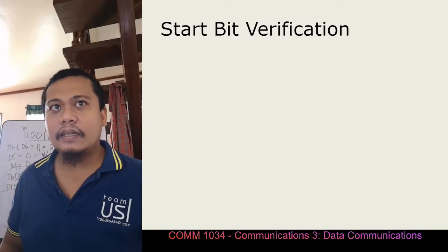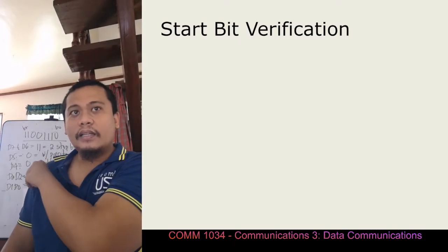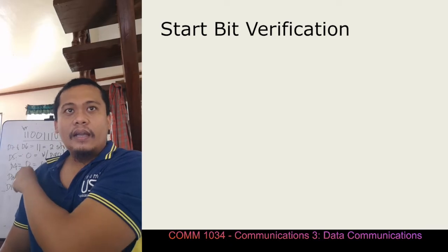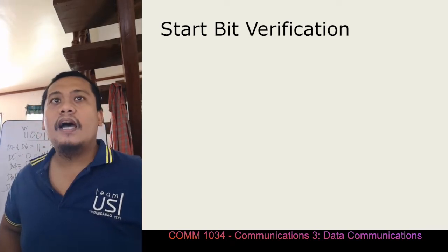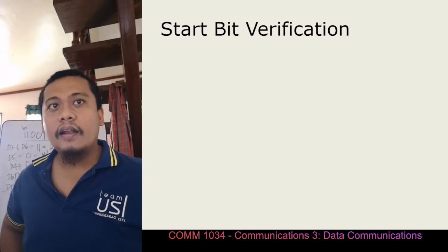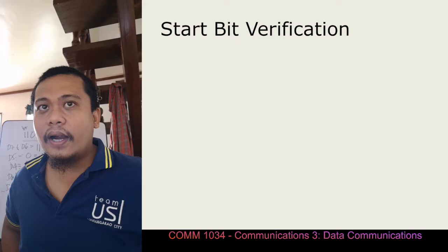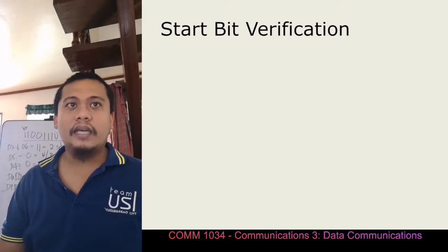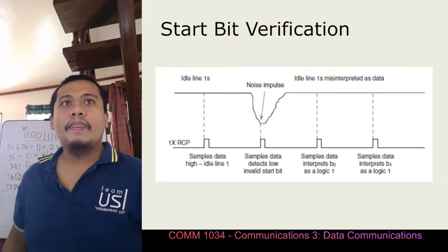Because data received by a UART have been transmitted from a distant UART whose clock is asynchronous to the receiving UART, bit synchronization is achieved by establishing a timing reference at the center of each start bit. Therefore, it is imperative that a UART detect the occurrence of a valid start bit early in a bit cell and establish a timing reference before it begins to accept data.